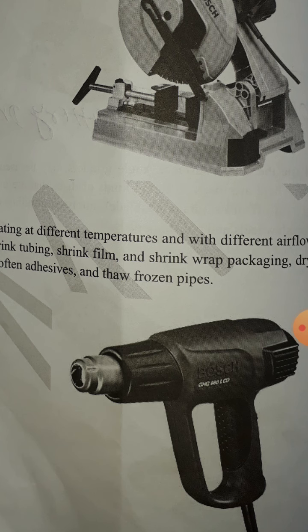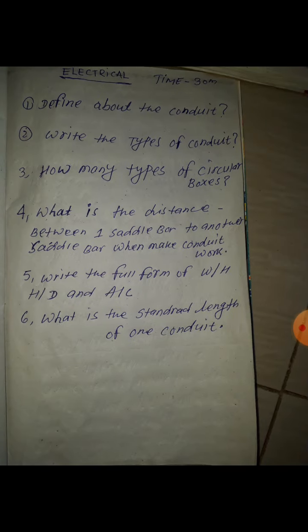If your cable core is red, you use a red sleeve. If your cable core is black, you use a black sleeve. The sleeve is small or big, so you heat it with the heat gun and it catches onto your lug with the conductor. Okay, so that time you use the heat gun.